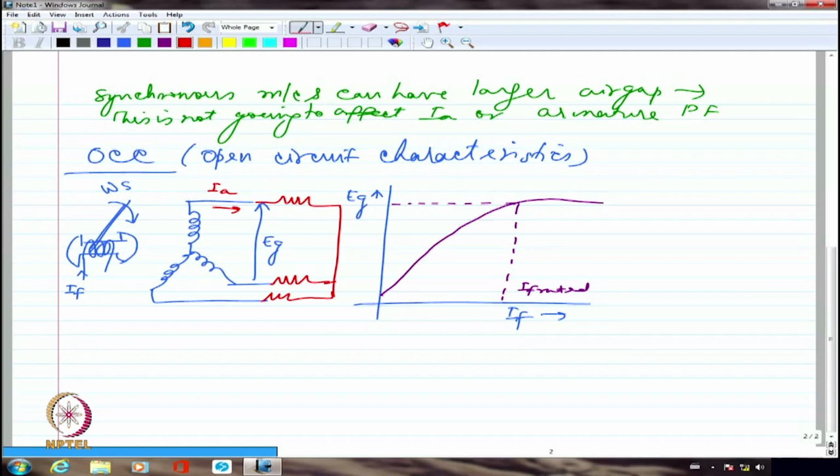In this particular case, I have one revolving magnetic field because of the physically revolving magnet. The rotor is revolving physically, and that is at synchronous speed. So that is definitely going to create a magnetic field which is revolving in nature. The other one is due to the three-phase currents that are passing through the three-phase winding of the armature, which is also revolving in nature. Now both these things are going to definitely induce EMF in the stator winding itself. Please remember, the stator winding is stationary.